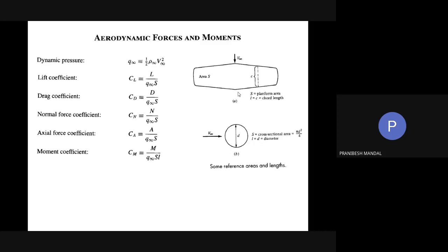If the aerodynamic object is your cricket ball, then the reference area is again the planform area of this particular cricket ball, and that is pi r square. So the object you are dealing with will actually define what your reference area is. Is it clear to you?